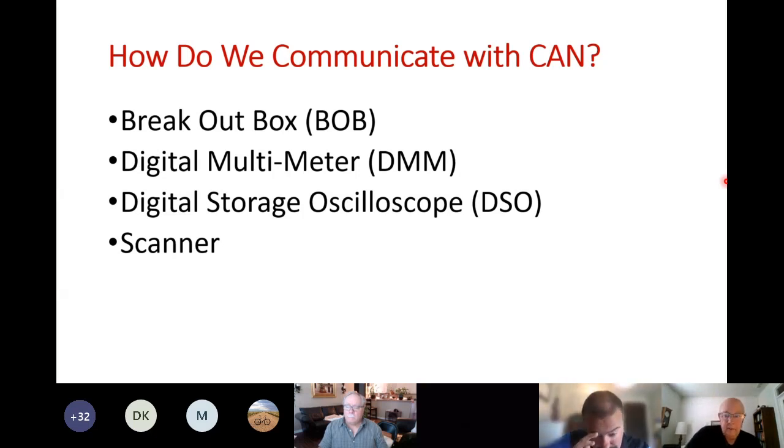Now, back up just one small little bit here. Realize that the pins in the connectors for the various modules, again, are made out of recycled chewing gum wrappers. You cannot connect and disconnect them more than 3, 4, 5 times, and then the connector has a bunch of opens and begins to see fretting. And once it sees fretting, then it's just absolutely not going to work that well.